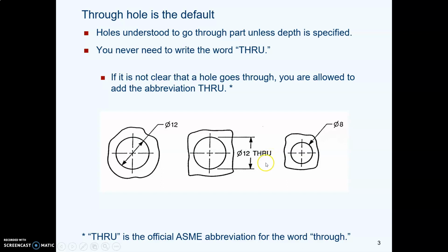There might be some times when you think somebody might be confused about what you mean. In those cases, it's okay to write through. It's not wrong. It's just extra work and you don't need to do it because a through hole is the default.